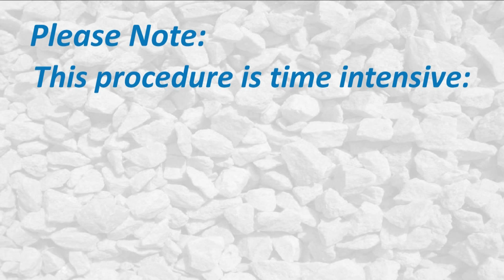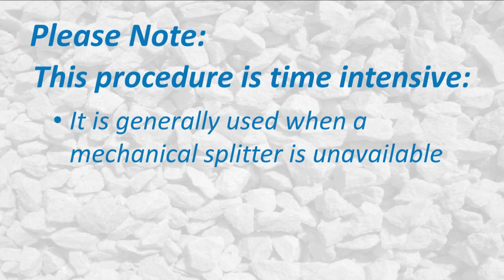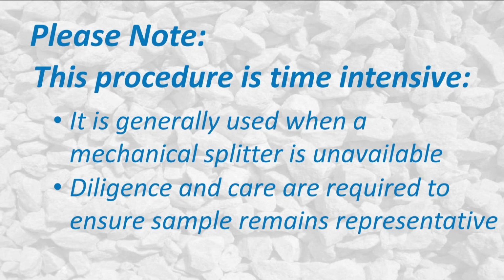Notes: the quartering method is fairly time-intensive and thus is generally used in situations where an adequate mechanical splitter is unavailable. Diligence and care is required to ensure that the samples obtained by quartering remain representative of the entire field sample.